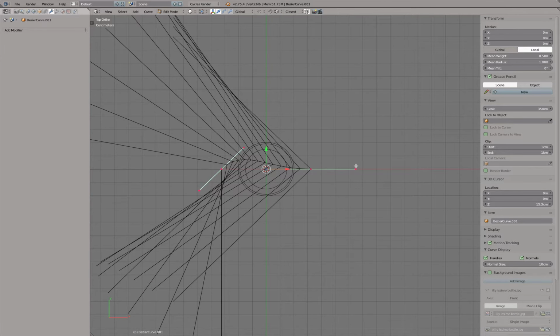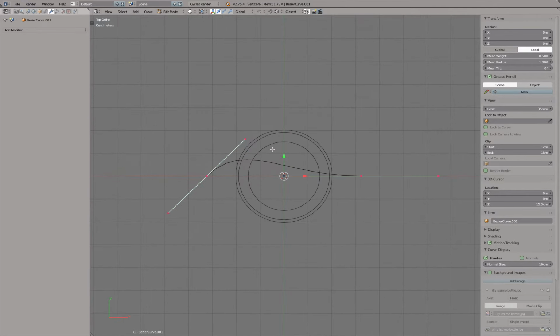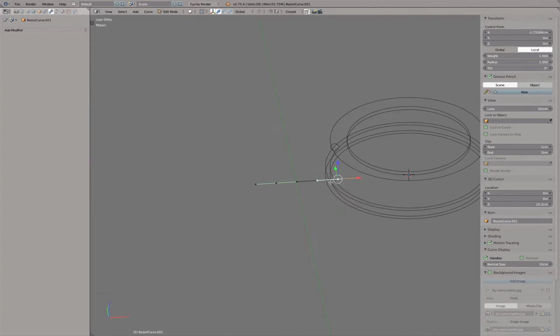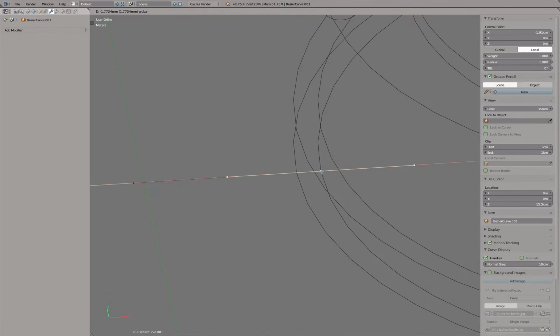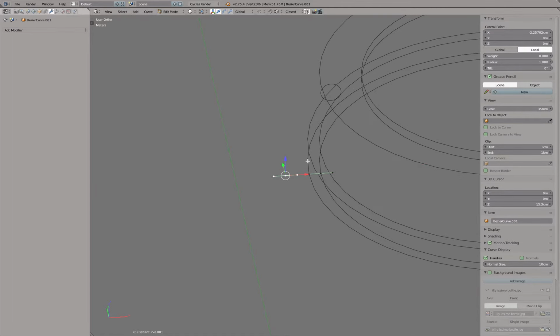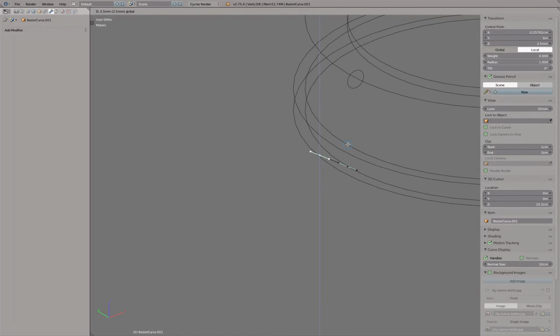I would like to turn off the normal view, so let's turn off the normals. And then, for example, we can select these 2 points, press V and say vector for the moment. And then we can start like what we did before, moving these points roughly to where they should be, and then with Control key, hold on to it. I'm actually not snapping to this point. I'm going to snap height-wise to this point, and then I move it along the x-axis to there.